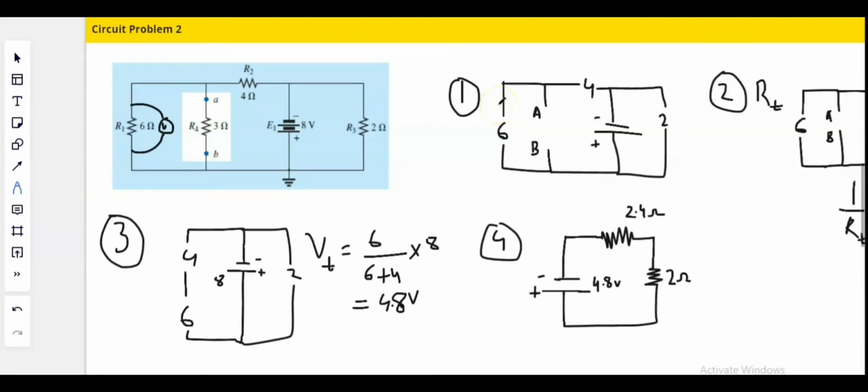But Thevenin's theorem has some limitations. It will only work for circuits that have linear components, and it will only work for experiments that are being investigated on a single resistor only. And if you're wondering what linear components are, they are basically resistors, capacitors, and inductors, while non-linear components are semiconductors, diodes, and transistors. So be careful of that.